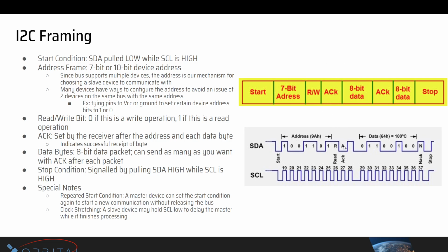And you can see in the diagram, this is going to be low. So the bus master, after the read write bit, would just let go of the bus and it'll idle back high, unless the device that you were talking to explicitly pulls it low to acknowledge that I received the address that you sent and the start and read write bit.